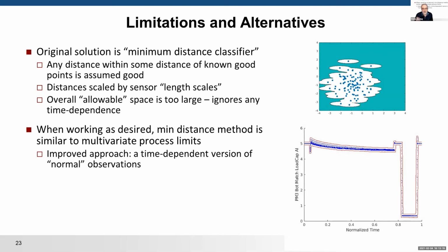And so if that overall space is too large, and in particular, if the time trajectory of a cycle traces out a big region, throwing away the time trace part, then you've got just really big limits, and you won't be able to detect a particular point that might have been anomalous at that time point in the cycle, given these expanded ranges.